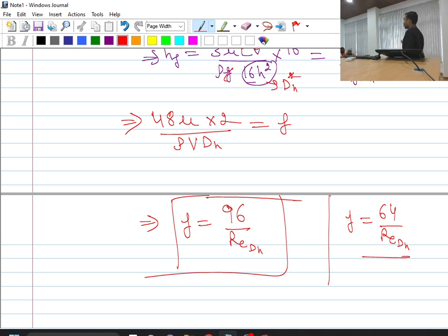on hydraulic diameter. So it means that under the laminar flow conditions, if I just do the replacement of hydraulic diameter into the circular duct formulation, it will be giving me some value of friction factor, but that will not be exactly correct. Because if I simply replace the diameter with hydraulic diameter and just use the relation of circular duct which we have theoretically derived, then it is showing me significant error. Why significant error is coming into this scenario? Because the velocity profile nature will be significantly different.